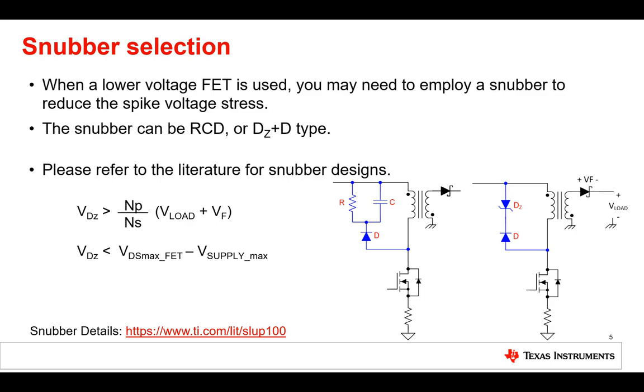The snubber works good, but might be somewhat expensive, and due to cost reasons, exchanging it with an RCD clamp might be necessary. For detailed snubber design, have a look at the application note Snubber Circuits Theory, Design and Application from Philip C. Todd. Although it is not new, it is still very interesting to go through.